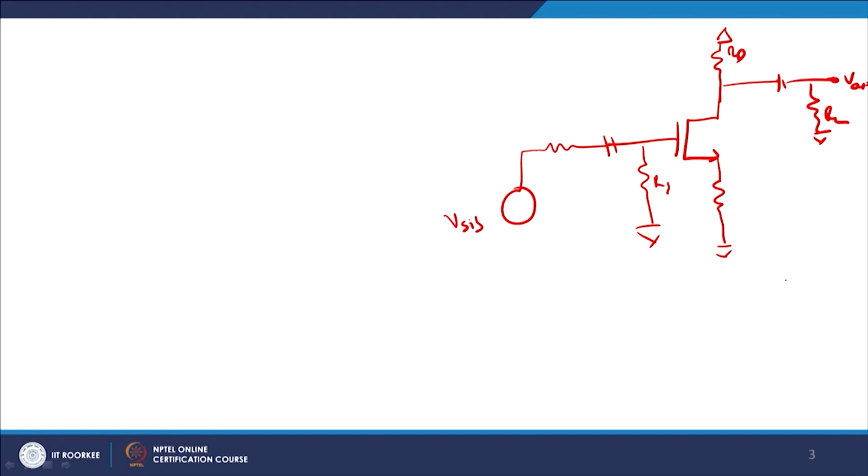Under this criterion this is also referred to as source resistance Rs, and what happens is that the effective resistance seen from the source side is basically 1 by gm plus Rs. So, if you look from the source side, which is the source end of this MOS device, the effective resistance seen by the device is 1 by gm plus Rs. With this knowledge, let me write down Rin, that is Ri, almost equal to Rg, because the gate resistance is the largest one and you get this.